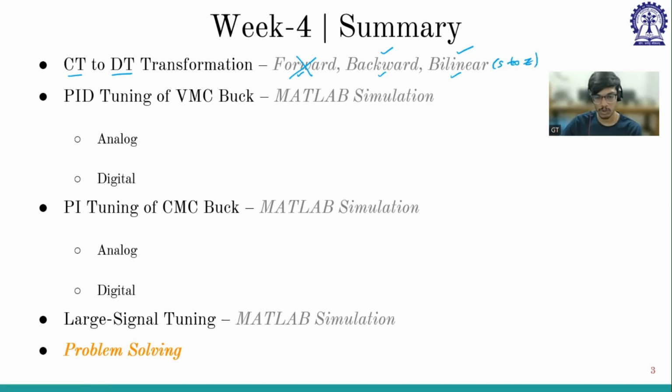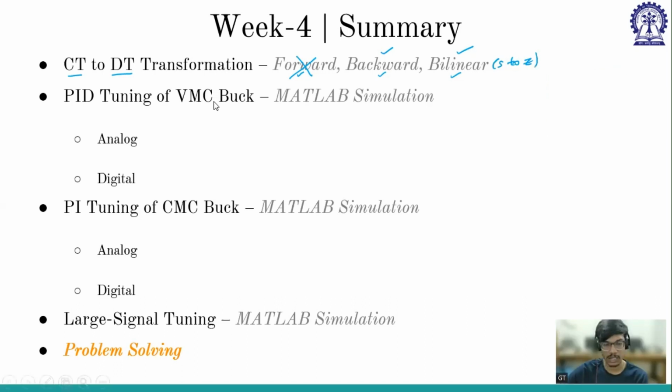Coming to the next discussion, we discussed PID tuning of voltage mode control. In analog, we used the continuous time model, and in digital, we used continuous time with delay, which is sufficient to design a controller. Same with PID tuning of current mode control. Here we have continuous time with delay. The additional TAUD model will affect only the phase margin; the others will be exactly the same as analog.